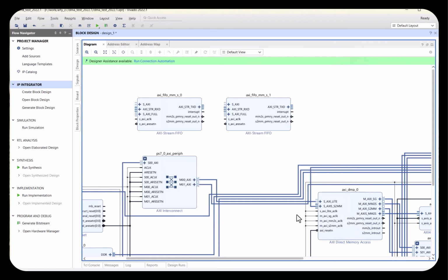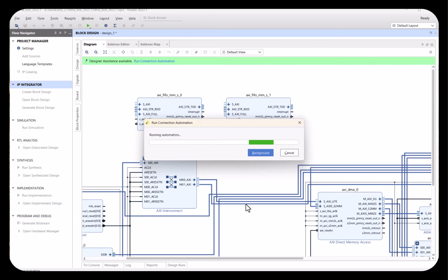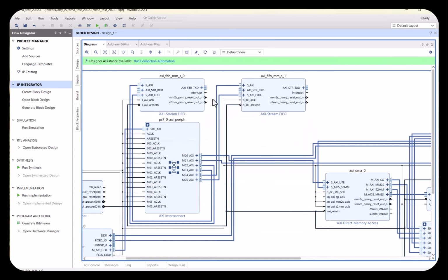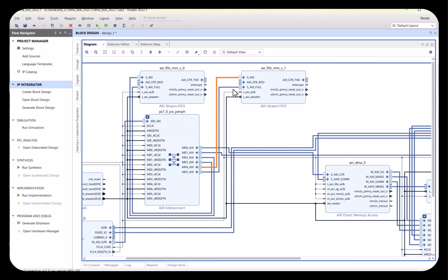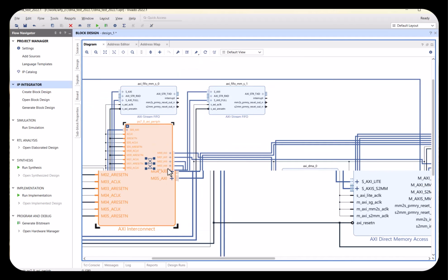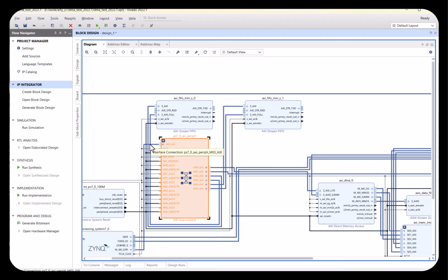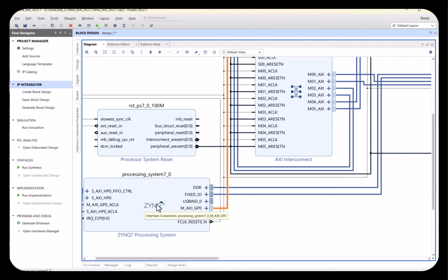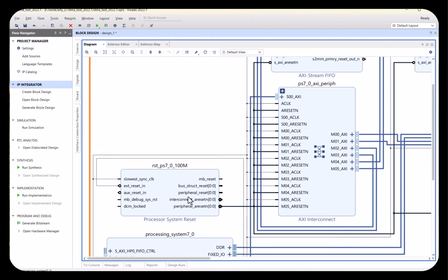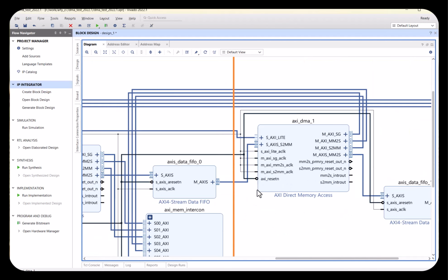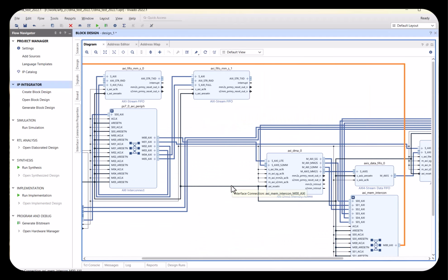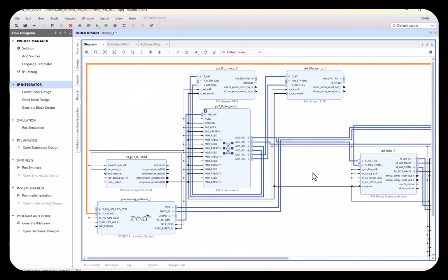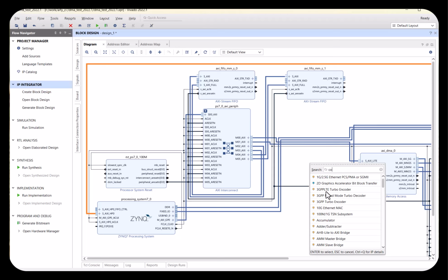and it'll go to the original AXI interconnect. So what do I mean by that? Look at these two ports. They go to this AXI interconnect, and this should connect to the GP0 of the ZYNQ. Now HP0 goes to the DMA controller. So now that this is done, we have to connect the interrupts. So we're going to add a concat IP.